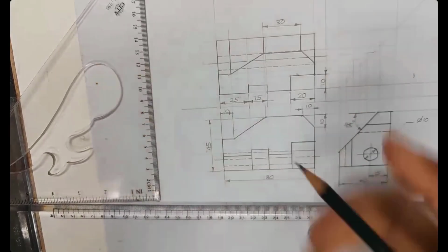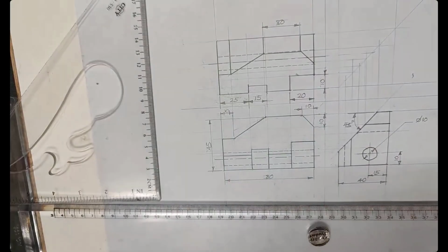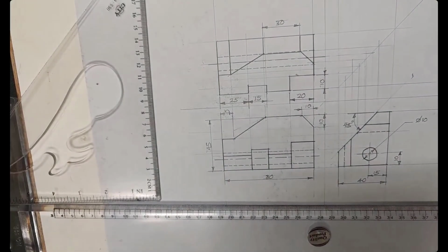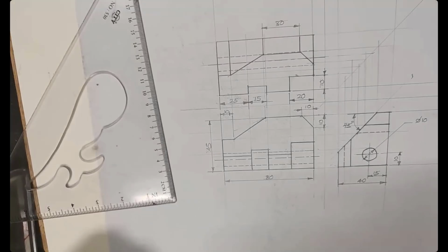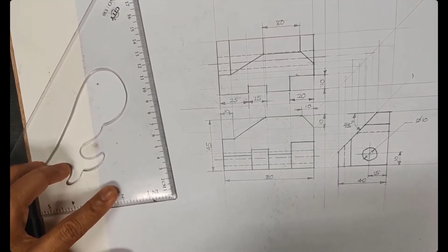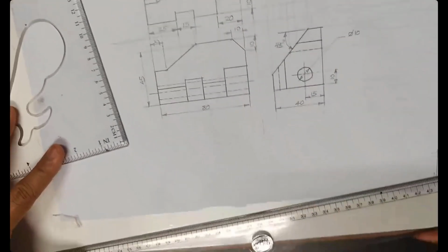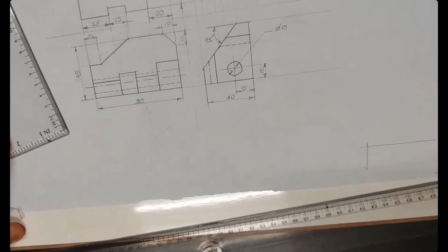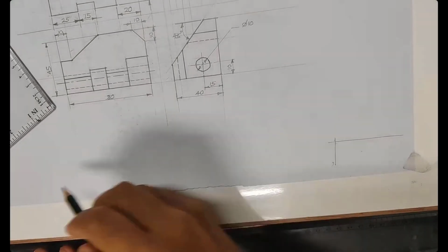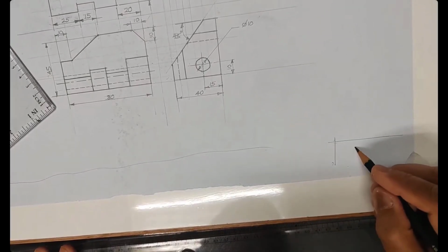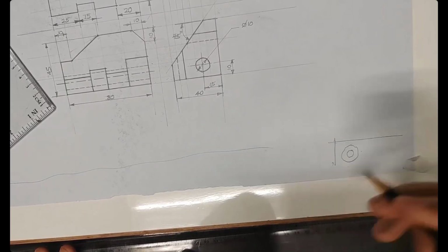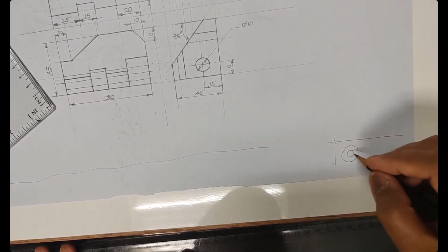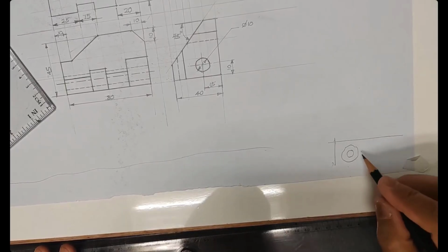I stop it here. Make sure the dimension is complete. Okay? Yes, sir. Make sure the title block is there. Remember the title block at the corner here. Are you watching or not? The title block at the corner there. This is your title block, right? Title block, corner, third angle symbol. The way I already showed in class, what the dimension is, on your slides, right? Look at that. I already showed in class.